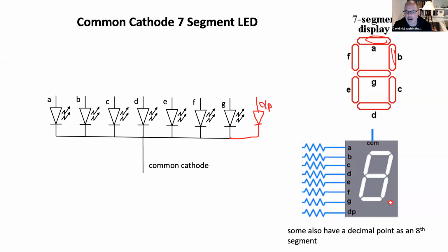All right. So it's got 7 LEDs built into the package, and they all share a common cathode. You can think about that as a common ground or a common negative terminal. You remember from last time, we talked about how the anode is positive and the cathode is negative when you polarize this, and current flows from the anode through the device, and it causes the device to glow, to give out photons at a frequency that depends on the particular semiconductors used to make the LED.